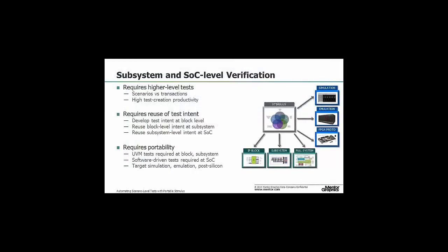So you're probably well aware that SOC verification is significantly different than block or subsystem level verification. At block level, everything is very much focused on transactions, individual transactions, and coverage. The goal is to generate lots of transactions to get high coverage, both code coverage and functional coverage, as quickly as possible. Now, when you move up to SOC level, the objectives change quite dramatically.